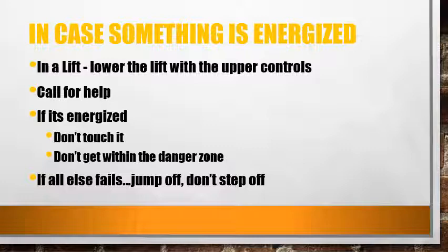If you are on the ground and someone is in a lift and it's energized, do not touch the lift. Don't even get within a 10-foot danger zone of the lift. If you are in a lift and it is energized and no one can rescue you, and a fire has started or there's a threat of explosion, if all else fails, do not step from the energized equipment, because stepping from it could create a path from your leg that is attached to the equipment and the leg that is on the ground, and your body would become the path of least resistance for that electricity. This is, once again, only in an all else fails type situation.